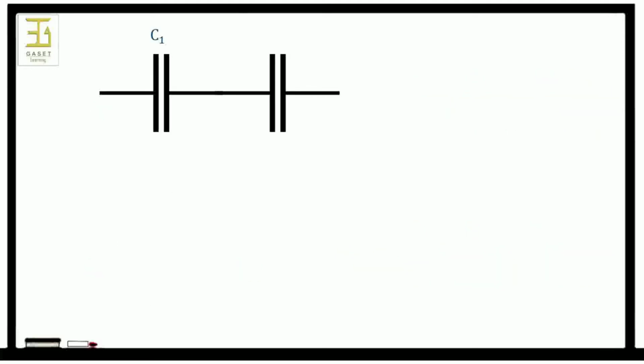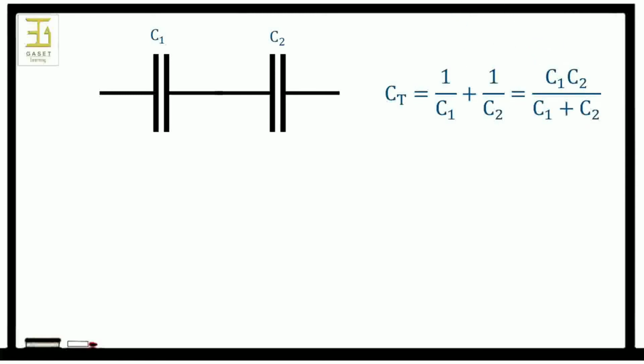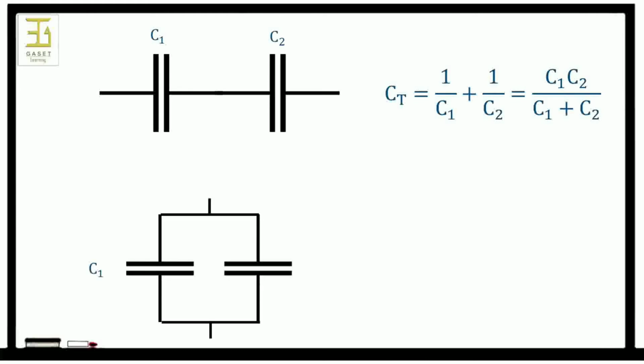What about capacitors? Now capacitors are a little bit different. They operate in a different way. The series capacitors has the same equation that we used before when we were looking at parallel resistors or parallel inductors. So capacitors in series, you use this relationship. The capacitors in parallel are easier. The equivalent capacitance between this point and this point is just the sum of the individual capacitances.